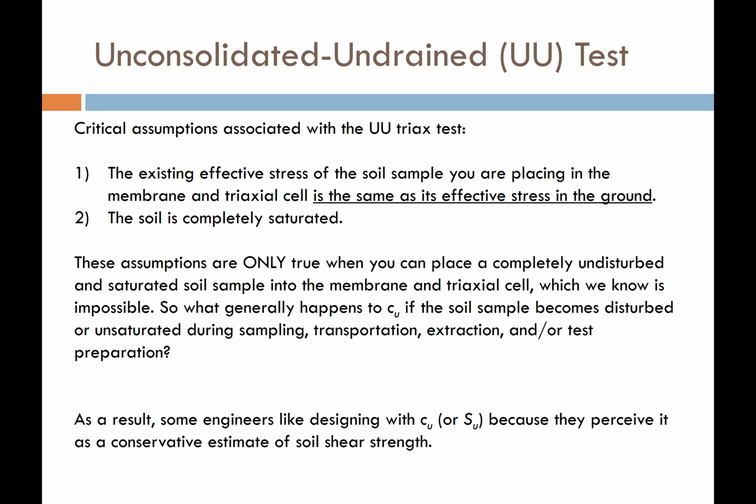So the UU test is really trying to simulate the soil immediately after a load has been applied, but before the soil has had an opportunity to consolidate under that load. So in order for that simulation to be true, two critical assumptions need to be met with the UU triaxial test.